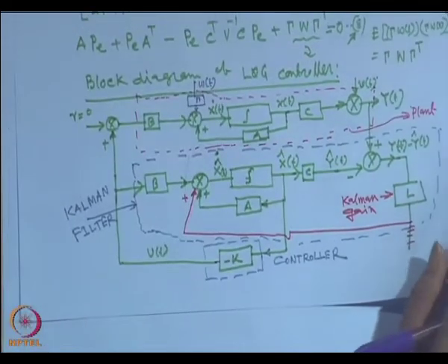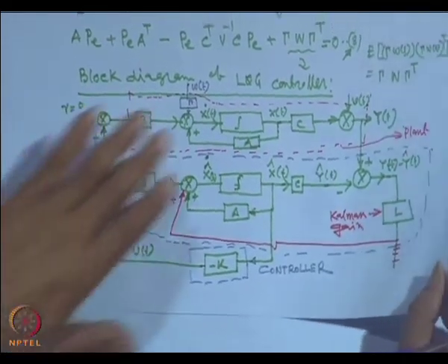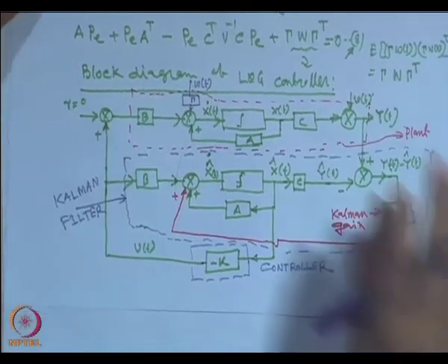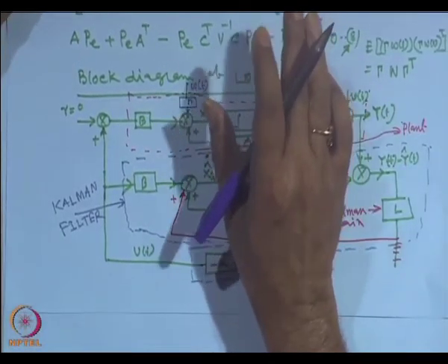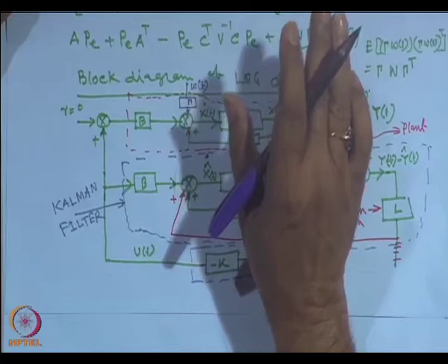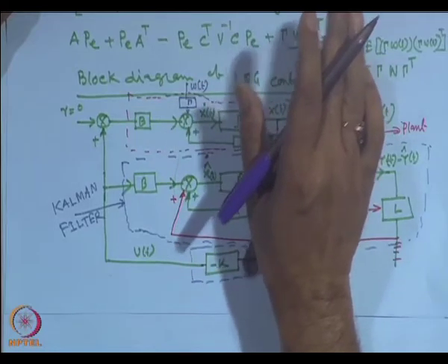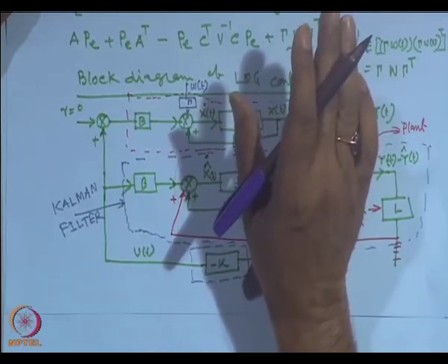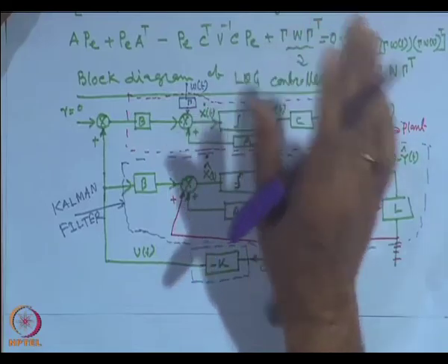Now, we will see what we observed in the LQR design. If you design the controller based on LQR, the gain margin is infinity: you can increase the gain to infinity, and at the same time reduce it to a half.